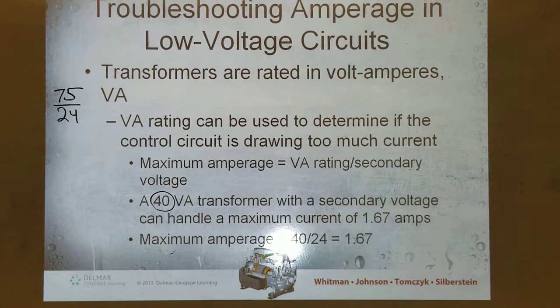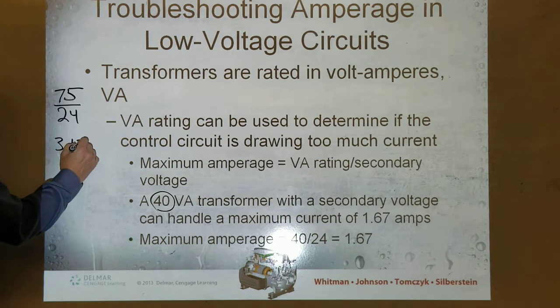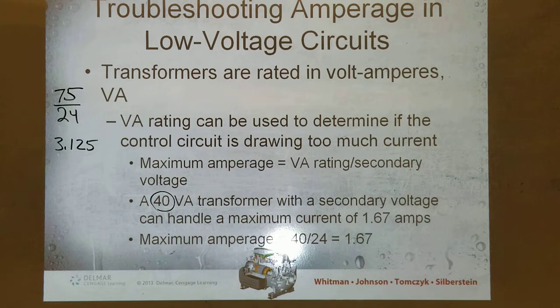Around three. 3.125. That's the maximum amp draw that transformer should be drawing in that control circuit.